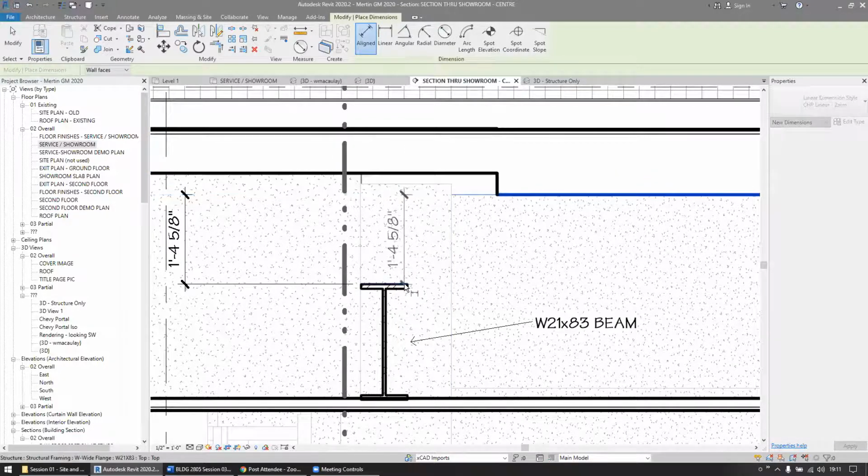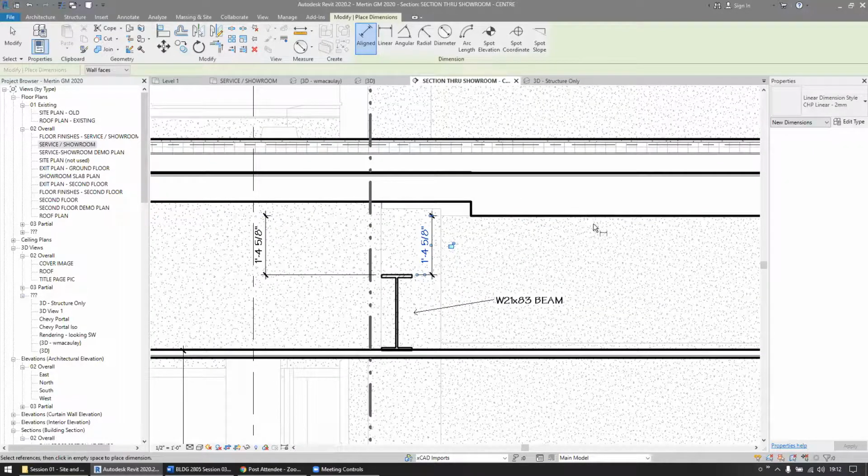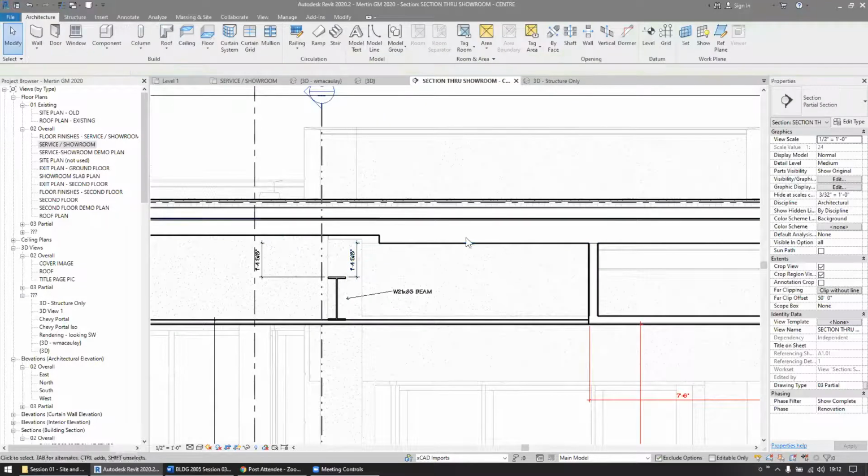Certainly not 24 inches, about 16 inches. So by the time you get that little connection flange around the outside edges of the duct, it couldn't be a 24-inch duct anymore. It actually ended up having to be a 10-inch duct because he needed to get some clearance underneath our new roof joists here in this zone.